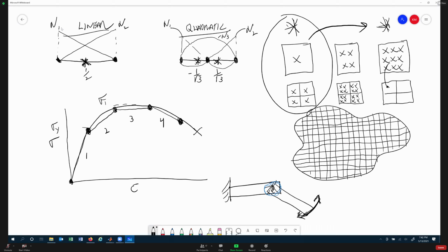Like fixed boundary conditions, or contacts: is it a bonded contact, is it a frictionless contact, like this joint right here, right? There are different ways you could define this pin. You could say that it's fixed, but if you say it's fixed, it's infinitely rigid. It actually really changes the stress results, versus if you changed it to a frictional contact, then this thing's going to swing.